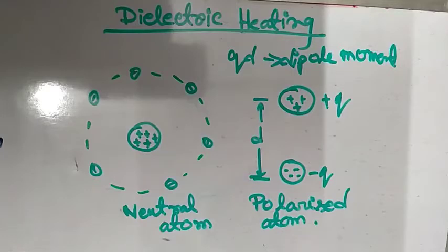Now, if an air gap is left, the air will be ionized and may result in breakdown. Therefore, it is desirable in dielectric heating not to apply high voltage but to use high frequencies. Even though voltages up to 20 kV have been used, from personnel safety point of view, voltages between 600 to 3000 V are more common.